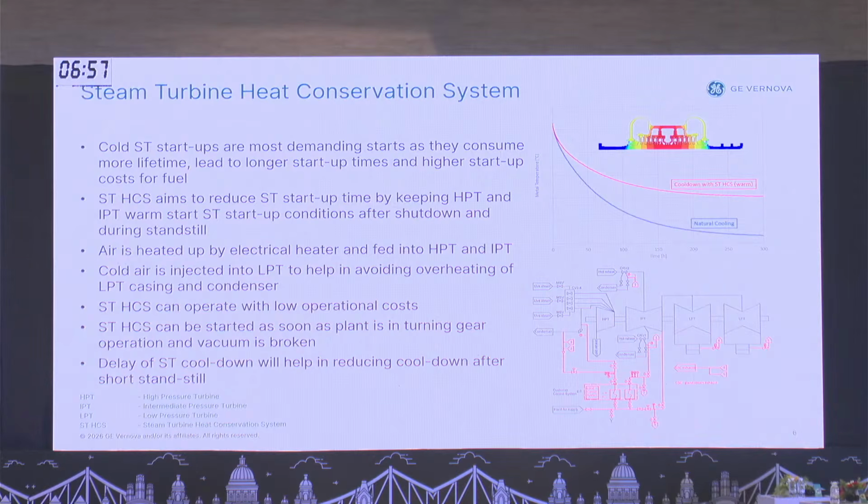HP turbine and IP turbine. And when it is injecting the hot air in the HP and IP turbine, actually it is warming up the turbine. It is warming up all the steam path for the HP and IP.